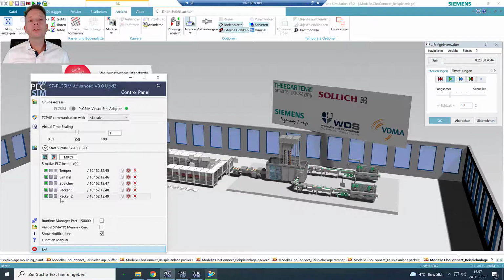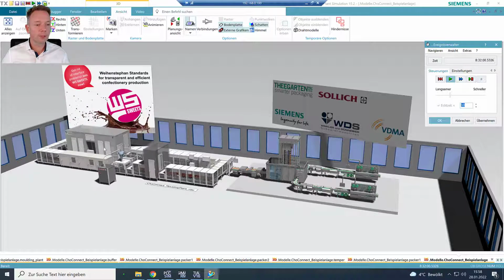Also, on all of those controllers, OPC/UA clients had been realized. This allows bidirectional communication from machine to machine without any central station above. For example, we realized the use case order control within the plant. Only one of those machines, the molding plant, gets the production order from a superior system. It starts the order and then it provides information of the input and output order currently processed to all the other machines.